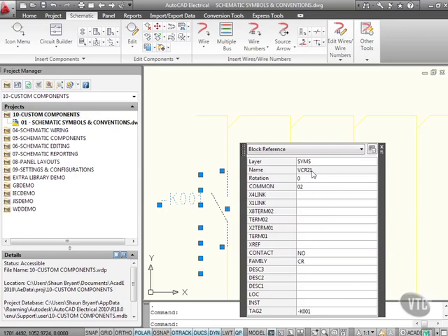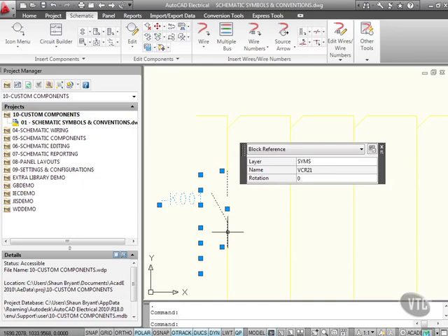Now, there is a naming convention for symbols in AutoCAD Electrical 2010. The V there stands for vertical, and as you can see, it's mounted vertically on that rung of the circuit ladder, and it is a CR. CR is basically a control relay. And then you've got a 2 and a 1. That normally indicates things like child contacts, or a 1 for everything else. So the 2 there indicates it's a child contact because obviously the parent is the wire there.